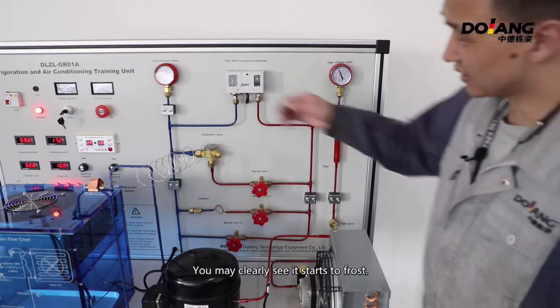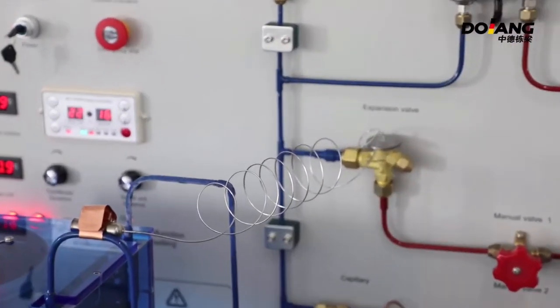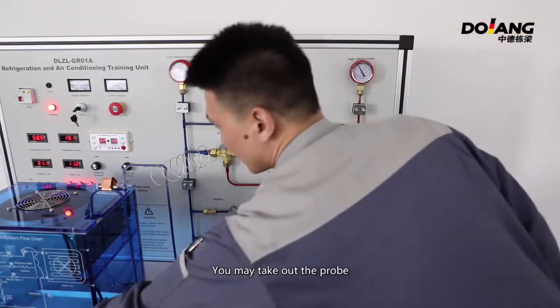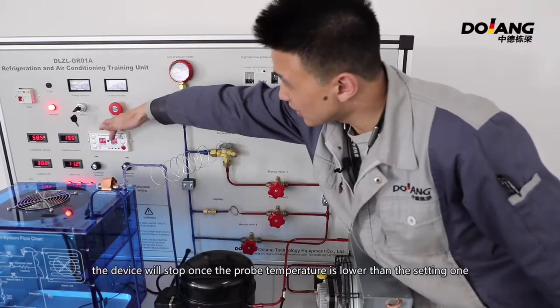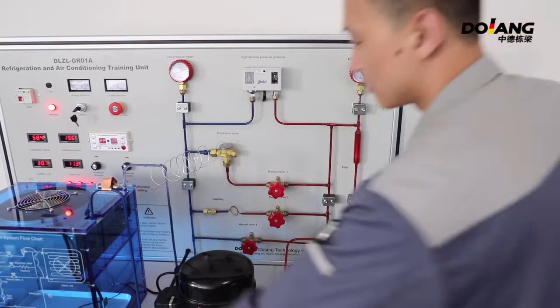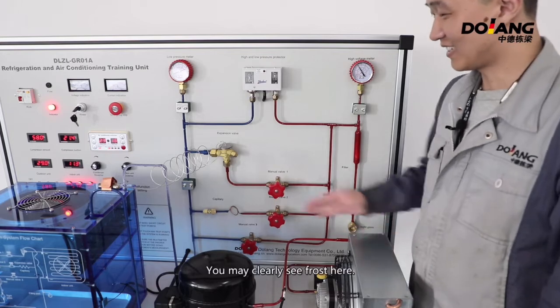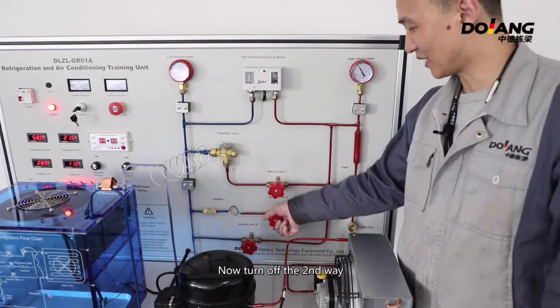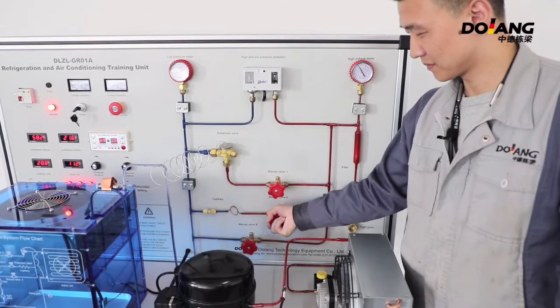You may clearly see it starts to freeze. If you need the device to run for a longer time, you may take out the probe. If you put it inside the evaporator, the device will stop once the probe temperature is lower than the setting one. You may clearly see frost here. Now turn off the second way. Do not turn off all the 3 way valves for more than 1 minute.